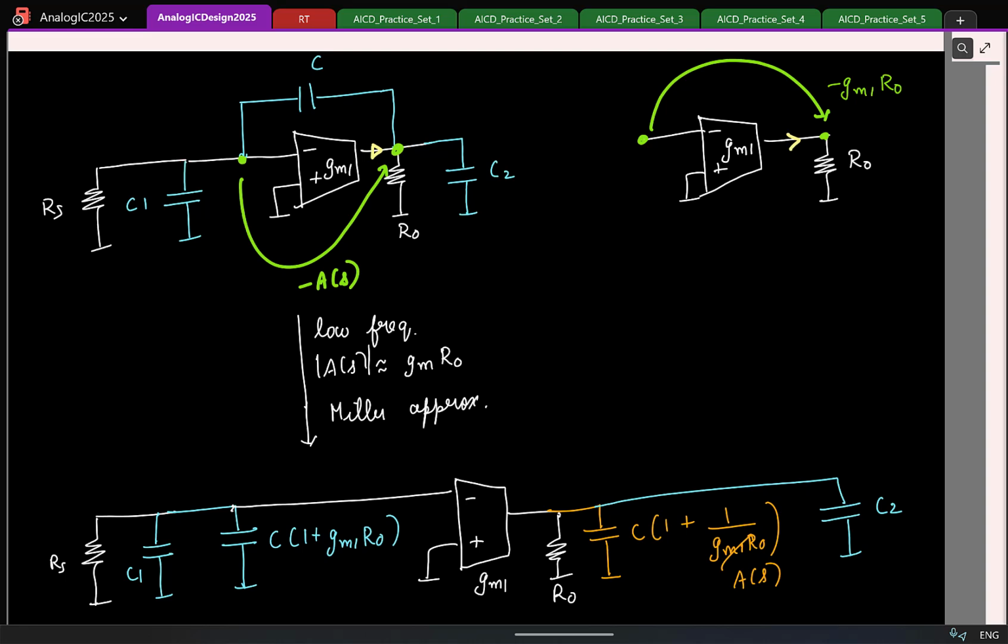So I could directly look at the capacitance and conductance at this node, and I was fine. Now the issue is that this capacitor is coupling it. But at low frequencies I decoupled it, and I could say the low frequency pole is this conductance by this capacitance. Similarly, let's see if at high frequencies we can write the pole as the conductance and capacitance at this node. But we cannot say this is the capacitance at the output. Let's see what happens.